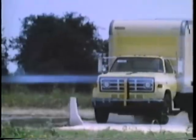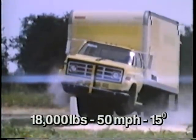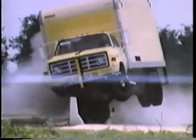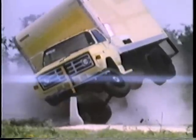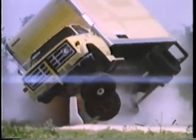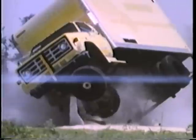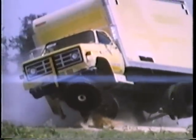The 18,000-pound single-body truck test is the most demanding test of barrier strength in the PL2 test series. In this test, the front of the vehicle rode up the sloped face of the barrier, then rolled 44 degrees until the cargo deck came in contact with the top of the vertical wall. Although the vehicle rolled over onto its side after leaving the rail, the vehicle was successfully contained, so the test was considered a success.